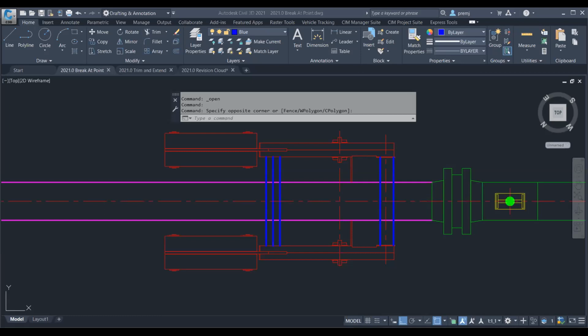Selecting the cutting edges or cutting boundaries was one of the things they made some good enhancements to in the past couple of releases. You really don't have to select anything. You can hit the enter key to select everything as your cutting edge. Now, you don't even have to do that extra enter key. While launching the command, it identifies the available objects on the screen as cutting edges by itself. I'm going to show that later in a little bit of demo in an AutoCAD drawing.